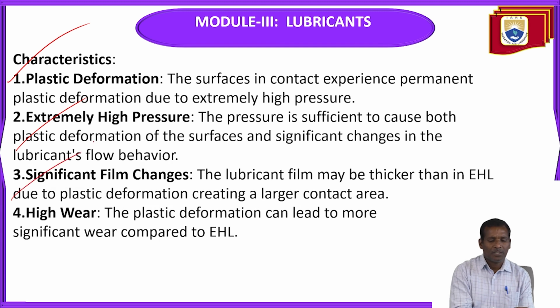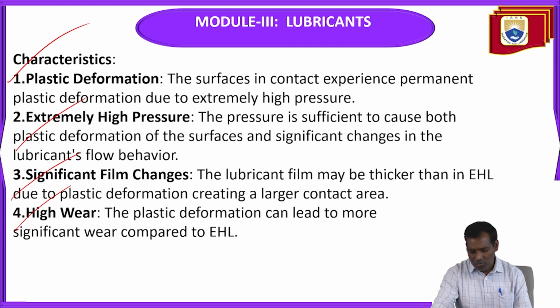Significant film changes. The lubricant film may be thicker than in EHL due to plastic deformation, creating a larger contact area. High wear. The plastic deformation can lead to more significant wear compared to EHL, elasto-hydrodynamic lubrication.